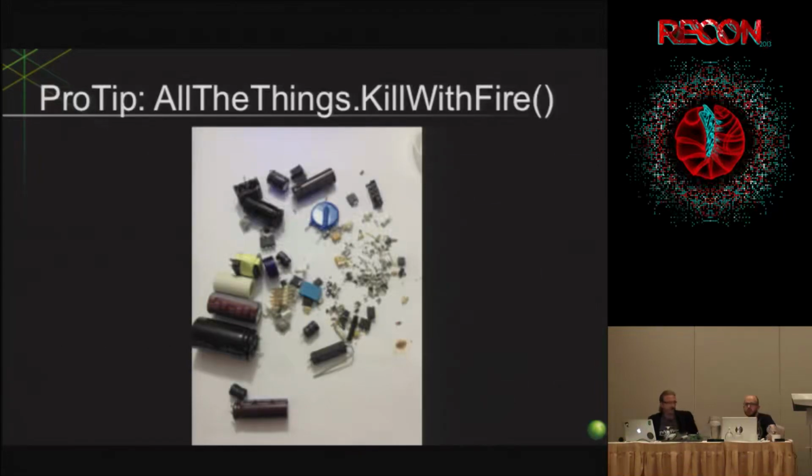I just take the hot air gun and remove every other component off that PCB. So I've got a bare PCB that then slaps into a flatbed scanner, and I do some high-res images from there. And then I throw those into GIMP or Photoshop and start doing tracing.